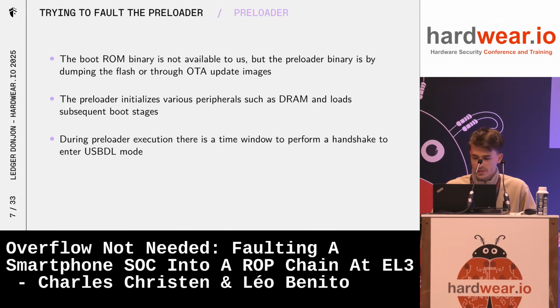But there is one thing that is interesting in the preloader. It implements a so-called USBDL mode, which is a command handler mode. To enter that mode, you just have to perform a handshake on the serial USB device that is exposed by the preloader. The handshake is just about sending the right bytes to this device.